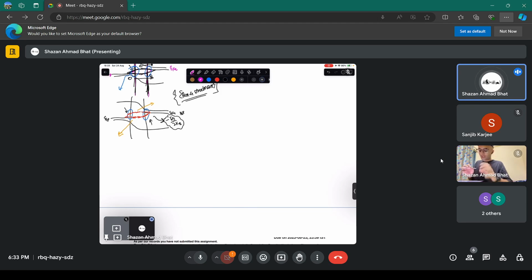When you do simulate it, you understand that most of the processes are happening at the particular regions where there is a slope in the Fermi level, because the gradient of this is going to give you the field. And then this picture directly comes from the electrons and the holes getting out of that region at these two particular regions.